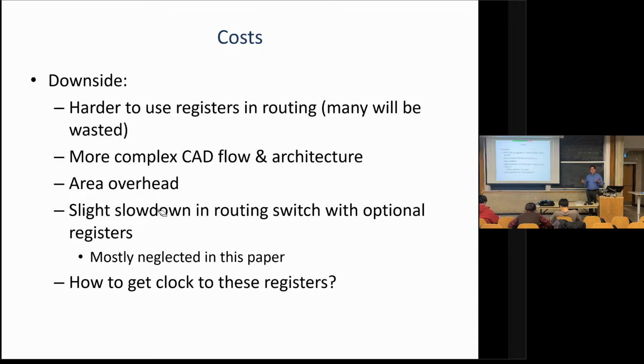If you actually pipeline so deeply that you exceed the logic block register count, the CAD tool doesn't know what to do with it. Now there is an option to say don't do that, which one of my grad students tried on that H-pipe design, the high performance CNN accelerator. The help says this option may reduce design performance and increase compile time, and it did exactly what it said.